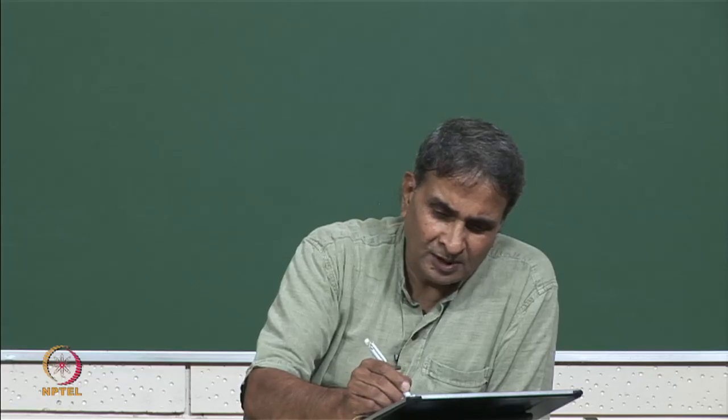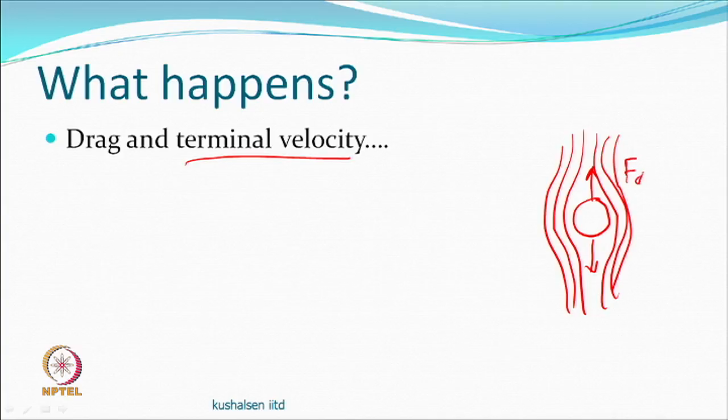But we are not interested in finding density. What we are interested in finding is the drag and then the viscosity, and knowing how they are connected. If you drop anything like this, it accelerates. If it accelerates, then it is very difficult to measure, it depends on where it started and where it has gone, and time becomes long. But fortunately, it does not happen. There is something called a terminal velocity. If we call this a drag force pulling up and the force due to gravity pulling down, they do get balanced at some point. And when they get balanced, it does not accelerate, it just moves with a constant velocity.